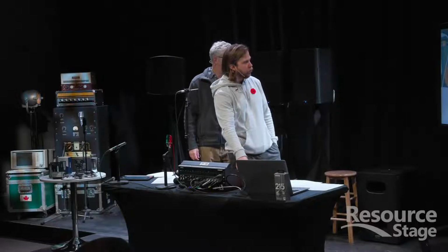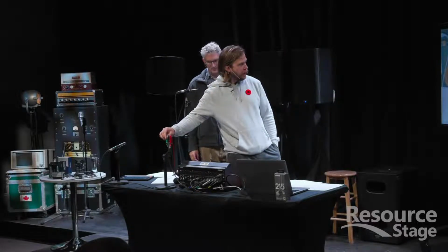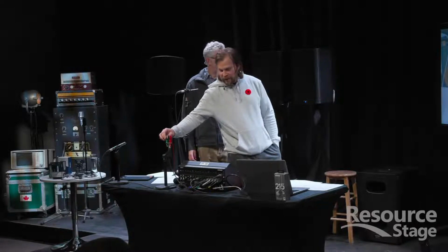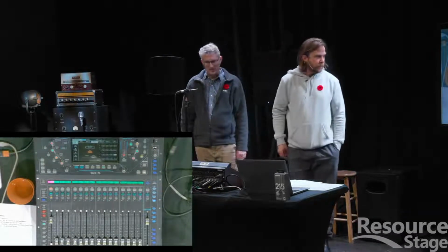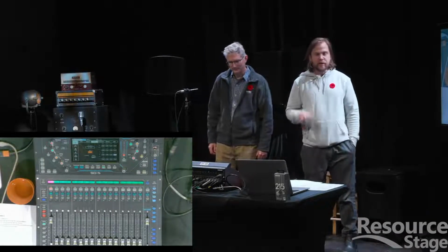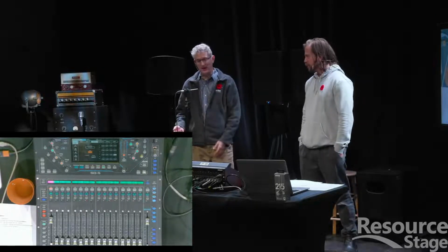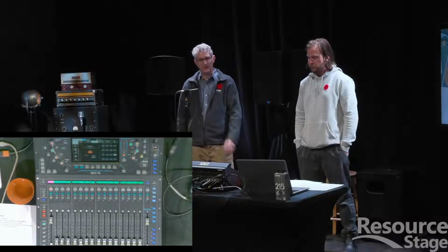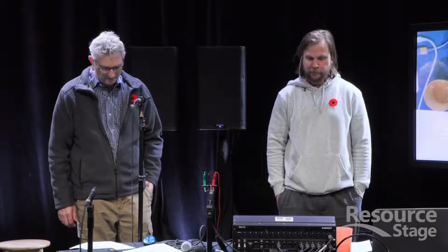Well, if we can get the overhead mixer shot, and we're soloed on this microphone, if our ground is making a poor connection, look at that meter. That's definitely not what you want coming through your sound system. So if you're getting really loud crackles and you have a condenser microphone, that's what you're going to hear. Very, very loud crackles, which is what Don didn't want to expose us to. That's right. And even with a dynamic microphone, you could have crackling problems like that if you've got a broken conductor. All right, I think we're ready to move on.